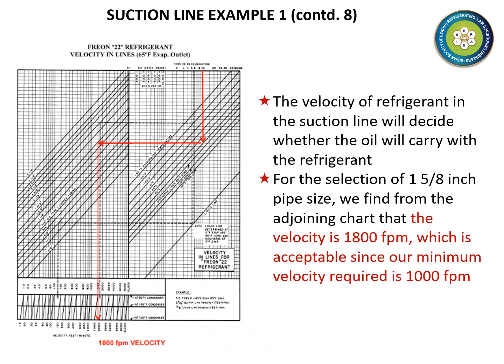On this slide, we estimate the gas velocity to be 1800 feet per minute, which is adequate to carry the oil along with R22 back to the compressor.